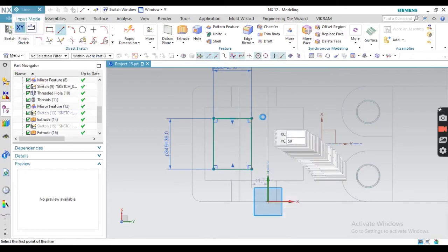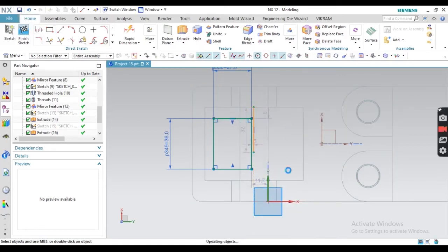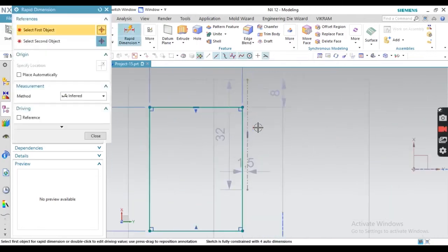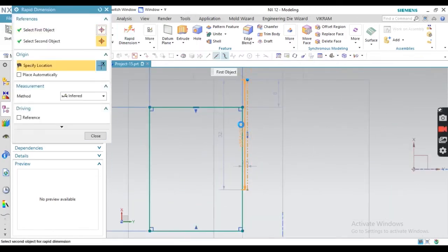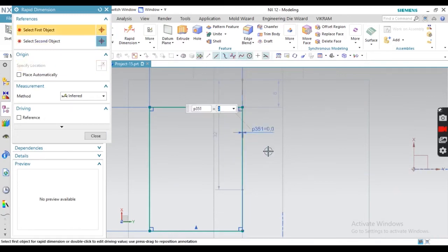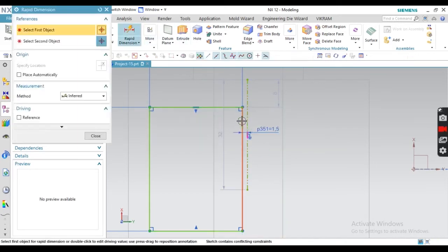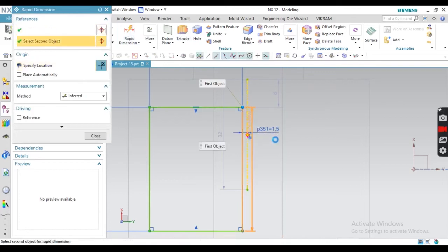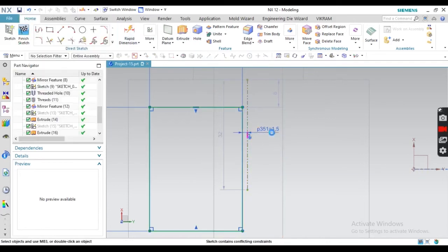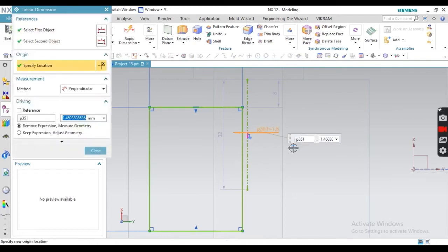Okay, next we have to align this with this center line. So I am creating the center line at the mid of this previous rectangle, and you can apply coincident or you can apply 0 values. Oh sorry, this line is moving, just fix it, because this construction line should be fixed. Now define 0. It's over constrained, a value is already given here, just put 0.